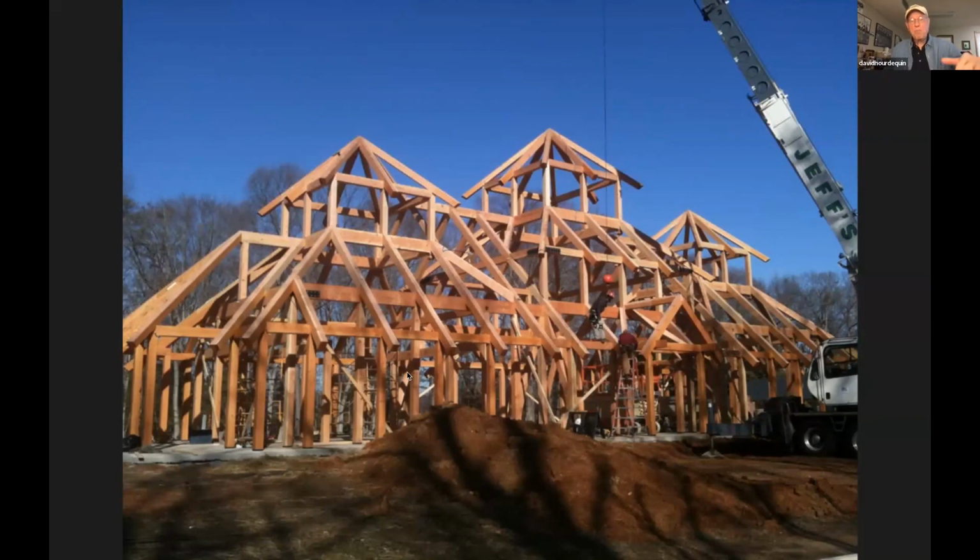Now, if this was an open pavilion, a completely open structure, then the open pavilion has knee braces in both directions from the post up to the trusses and to the plates. In that situation, when you have lateral wind load, those braces take the lateral load. You seldom would ever need sheathing up in the decking because the tributary area of the wind force going into a frame that has knee braces on it is usually fairly narrow. So you're not looking at a diaphragm shear situation of any consequence.